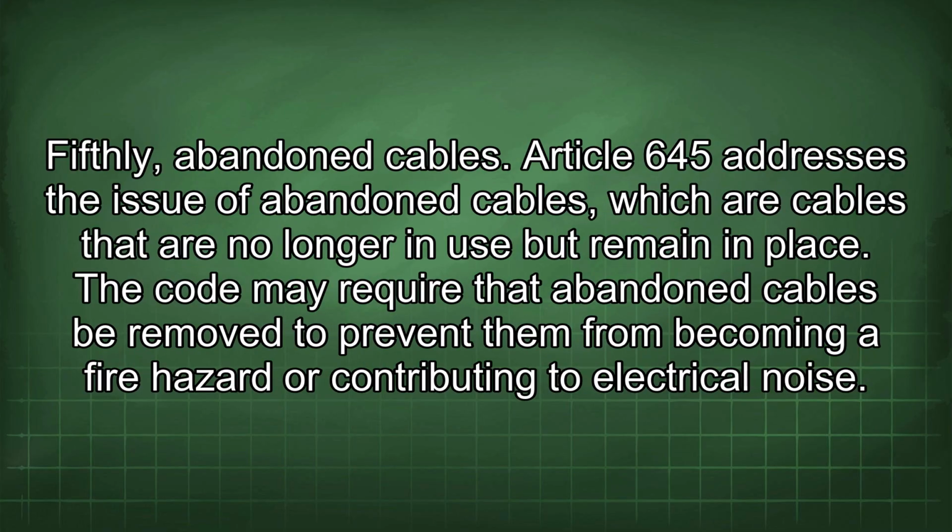Fifthly, abandoned cables. Article 645 addresses the issue of abandoned cables, which are cables that are no longer in use but remain in place. The code may require that abandoned cables be removed to prevent them from becoming a fire hazard or contributing to electrical noise.